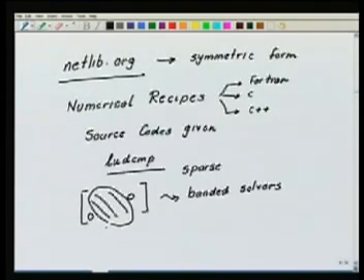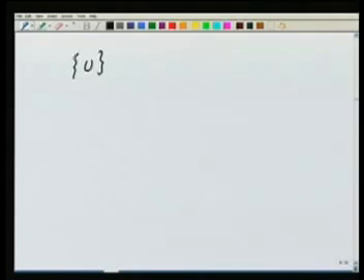Okay. So, there are these solvers which take advantage of that, and the elimination also I will do using that information. So, the cost of computation then comes down. Here one can also use the banded solvers. Okay. So, now we have obtained a solution, that is we have obtained these degrees of freedom u, which implies that I should be able to now get the finite element solution